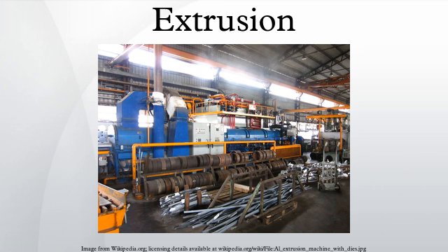Most hot extrusions are done on horizontal hydraulic presses that range from 230 to 11,000 metric tons. Pressures range from 30 to 700 MPa, therefore lubrication is required, which can be oil or graphite for lower temperature extrusions, or glass powder for higher temperature extrusions.